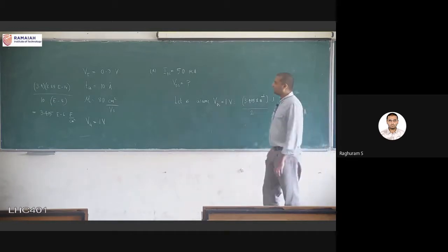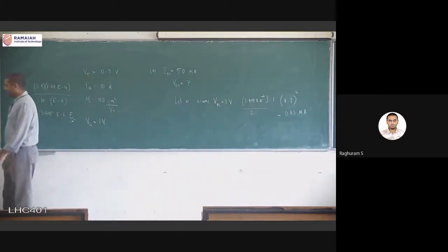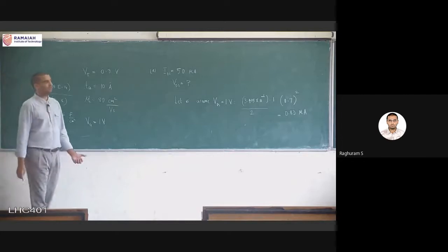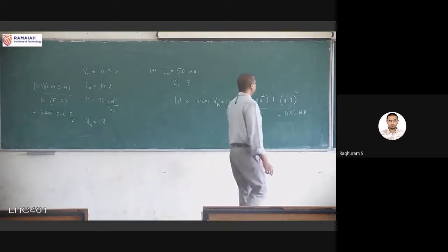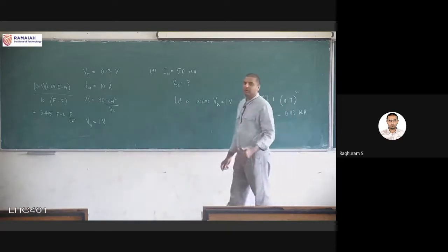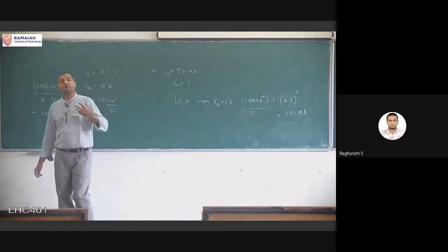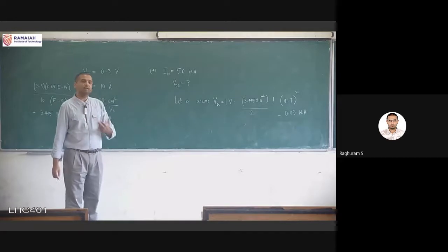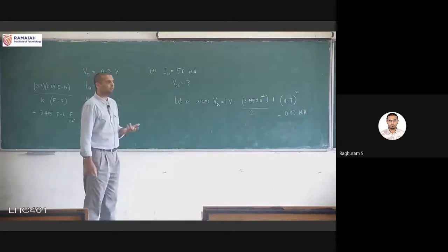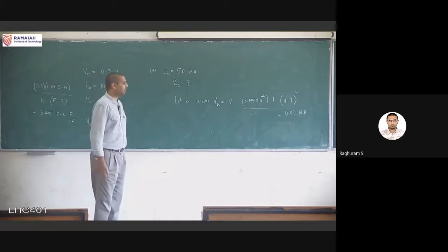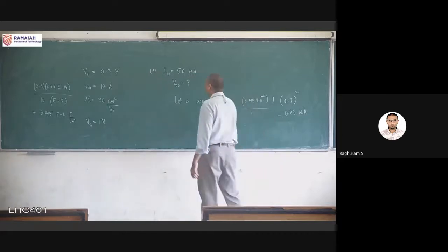So this is the problem. How are we going to ever get 50 microamperes? The problem with this is we don't have W by L. Right now we are getting this number, but we are using a very low value of W by L, W by L equal to 1. So now we have to assume a much higher value of W by L. Let us assume W by L equal to, say, 100. 100 is a very big number, but it is possible to have W by L equal to 100. And let us calculate for the same one. For W by L equal to 100,